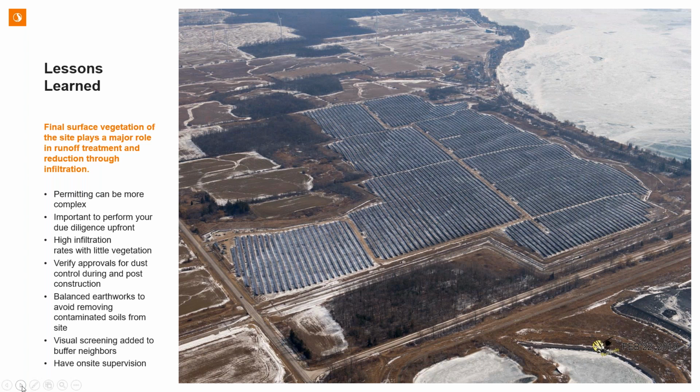High infiltration rates with very little vegetation on coal fields, for example, may be difficult to prevent soil erosion. You need to verify approvals for dust control during and post construction to make sure you meet your environmental requirements. Balancing of earthworks to avoid removing contaminated soils from site is usually quite important.